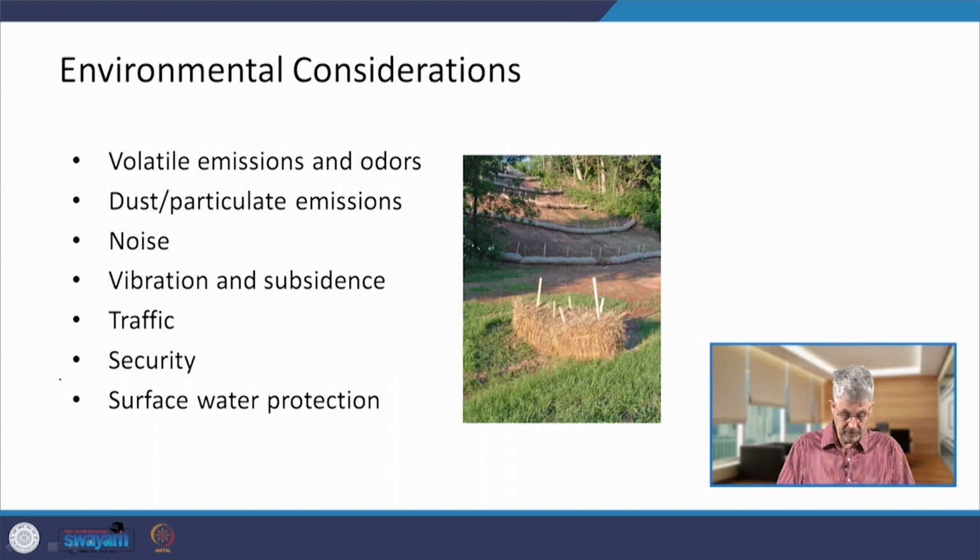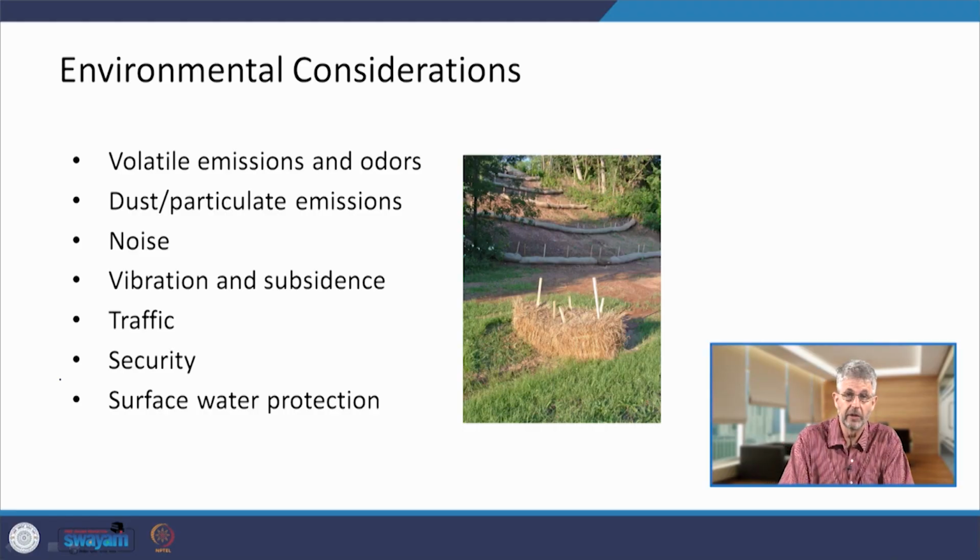And vibration and subsidence. Vibration means when you operate heavy equipment, rumblings may cause cracks in buildings. If you extract groundwater during your remediation, it can lead to subsidence issues where the soil is shrinking, again putting strain and eventually leading to breakage of slabs of concrete or basements. All this has to be considered, because if it happens, it's usually not a good thing for the person in charge of the remedy.